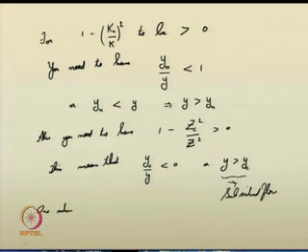One situation is that the depth of flow is greater than the normal depth, and the normal depth is greater than the critical depth. This occurs in a subcritical flow, that is, subcritical flow occurs in a mild channel. That can also happen.